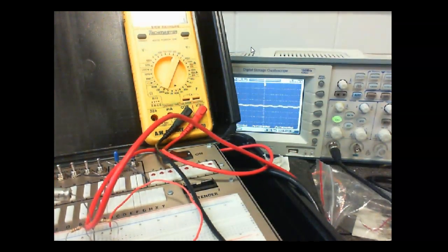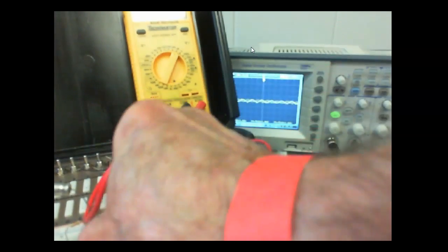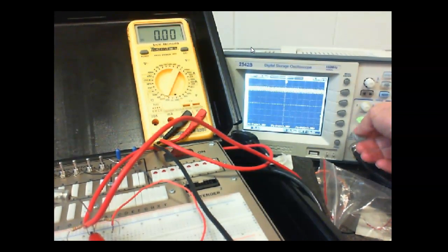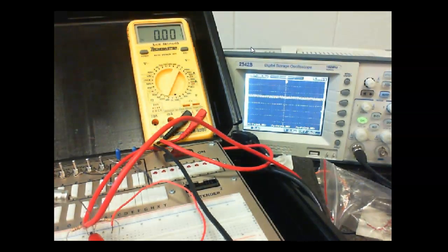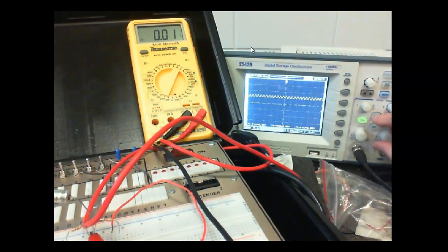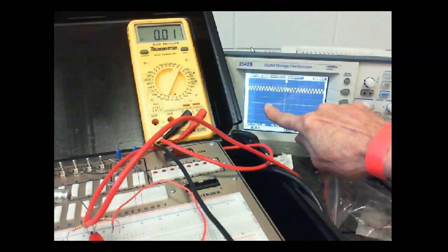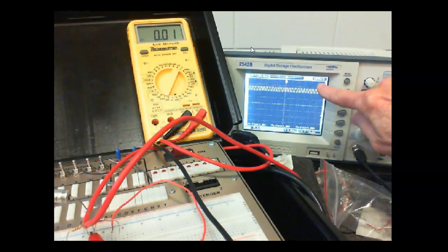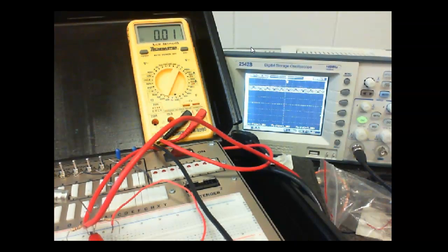But when I look at the actual signal itself, it's riding on DC. So there's the AC signal there. Here's 0 volts, here's 0 volts, and what it's doing is adding and subtracting to that bias voltage. So putting that capacitor in there allows me to bring an AC signal into the DC bias, and it's going to change the base voltage. When this voltage goes up, it's going to turn the transistor on more. When the voltage goes down, it's going to move it toward cutoff.